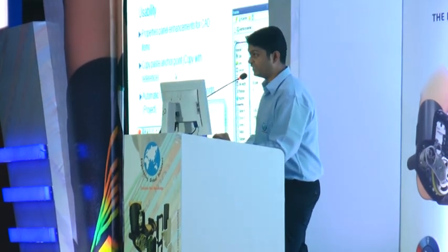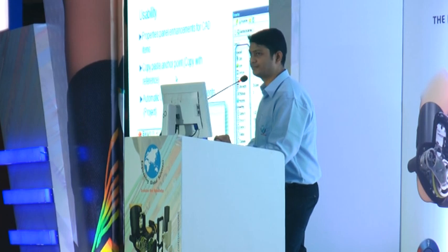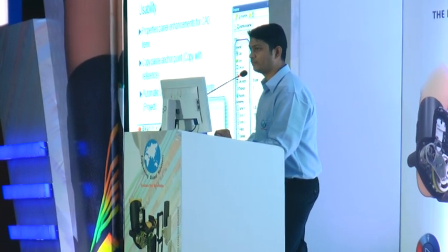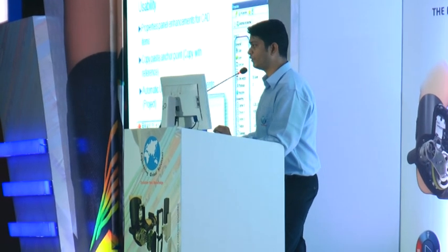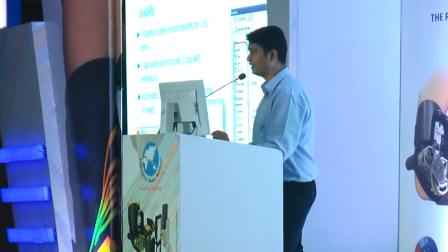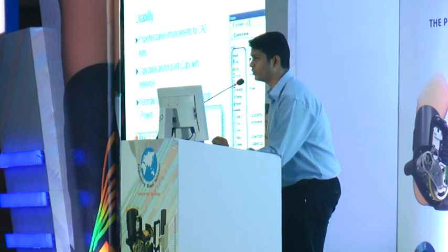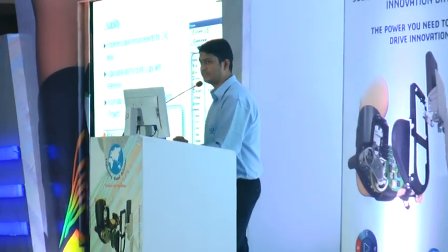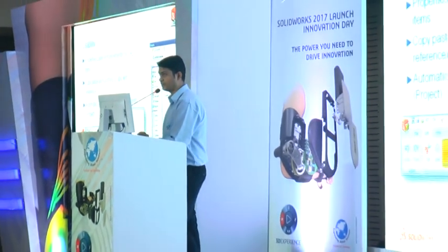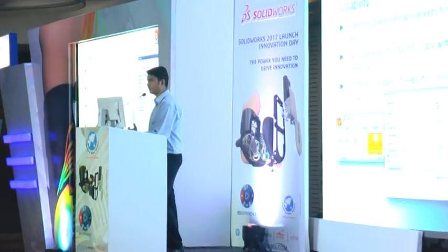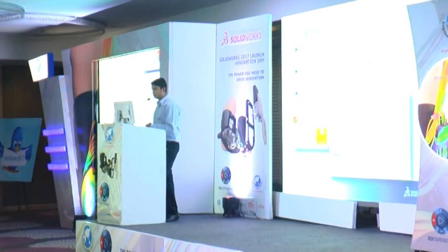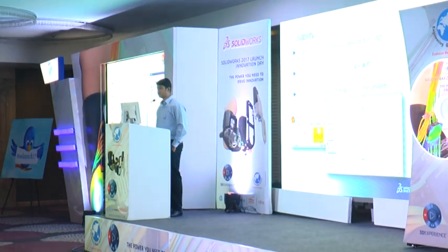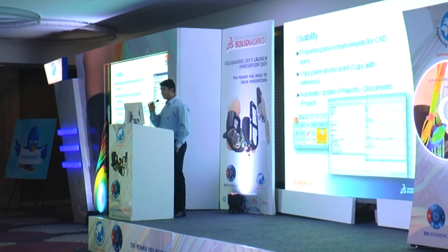I think many of them here are SolidWorks users right now. They can generate the BOM within a second. That is, the BOM gets generated automatically. Yes, SolidWorks Electrical also does that. It can generate various types of reports like list of cables, harness, manufacturer, cut length, cut list, wire length, and so on.